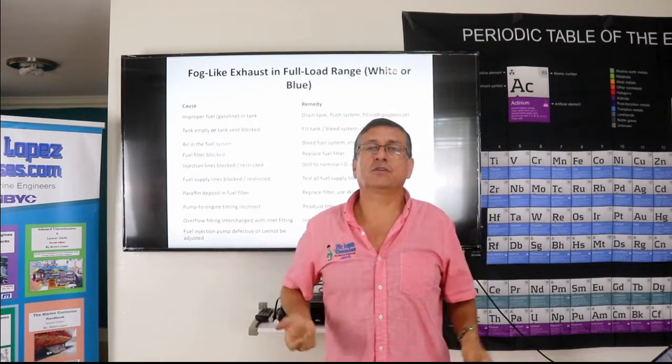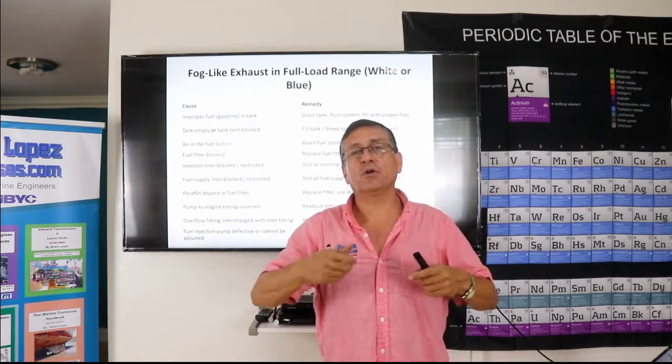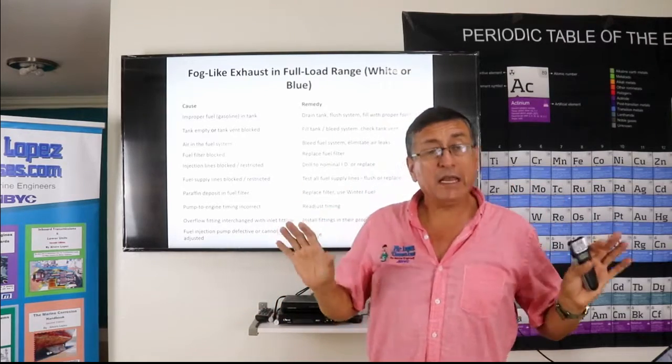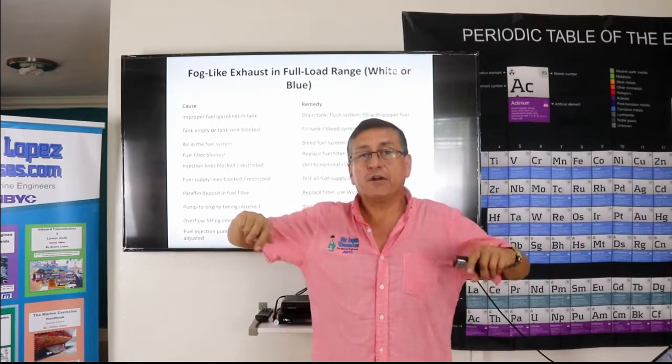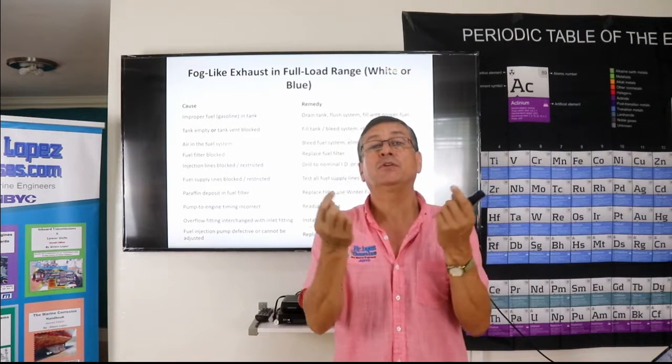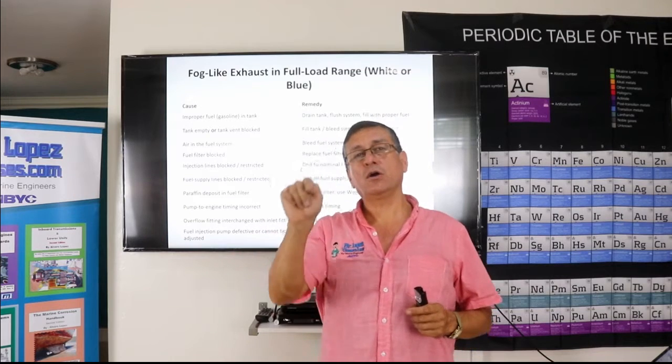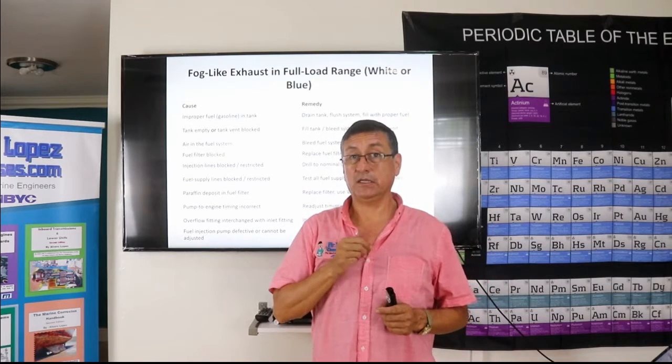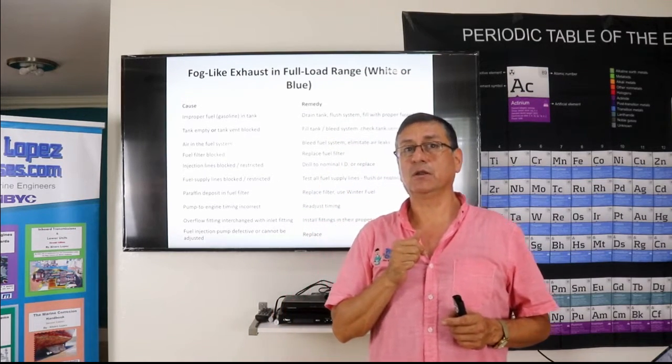Or, of course, if all the piston rings are broken, the oil penetrates. Normally, in normal conditions, the oil never penetrates through the piston rings because the bottom piston ring, the oil controller, returns the oil into the oil pan. You remember in chapter 8 about the lubrication system?